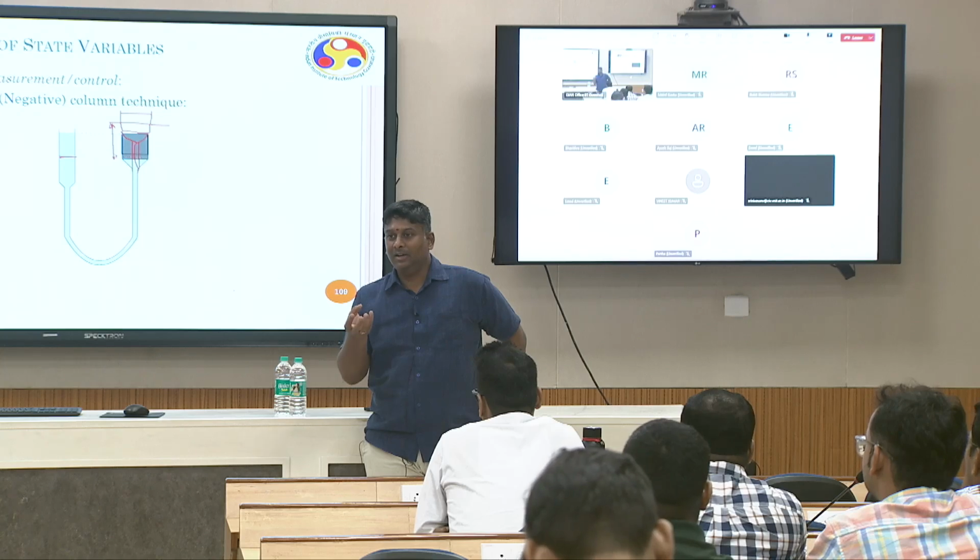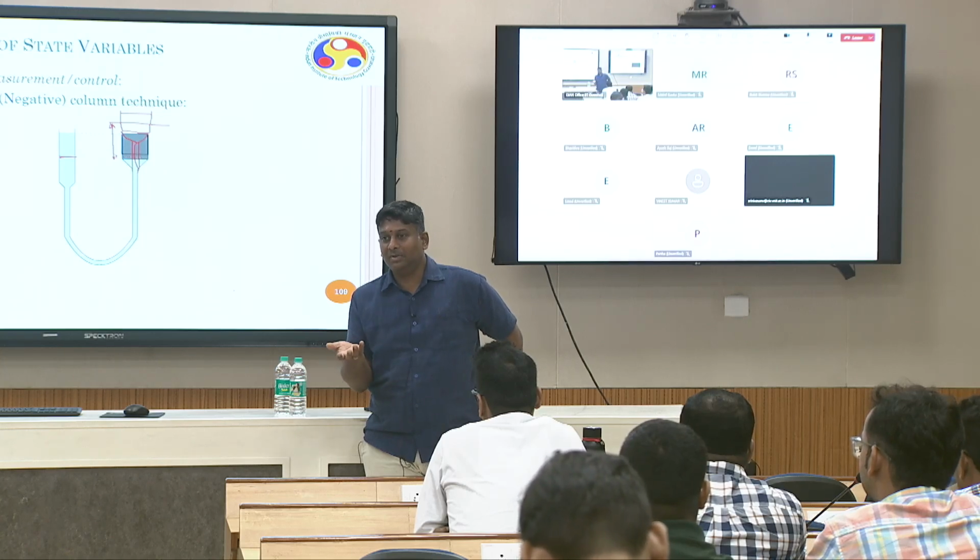And you are exposing the different soil samples to these RH conditions by maintaining constant temperature, and at equilibrium you are measuring the weight. That is one of the methods we use.